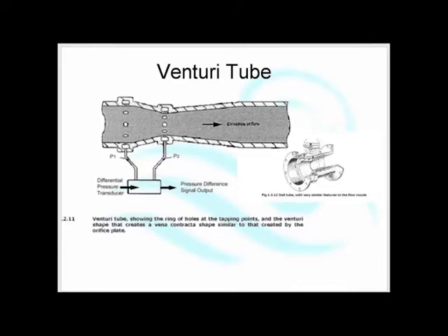And we do that by having a piece of pipe which is shaped like a venturi. And then in the middle bit just here, we have suction. If we compare the pressure at the middle bit with the pressure at the beginning bit, using a pressure sensor, then we know how much flow there is, because the more flow there is, the more suction there is in the middle. So by comparing the pressure using a differential pressure sensor, we know what the flow is.